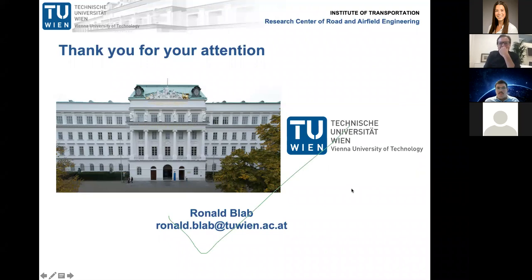Thanks for your presentation. I have a question regarding the input parameters for the macromechanic models. You mentioned that for the input parameters, you used the creep compliance. But normally in the lab, we have data such as the complex modulus and the phase angle in the frequency domain. Can we just directly use this as the input parameter? Yes, we can. We publish this. I can send you a paper. You can directly convert it, and it's no problem.